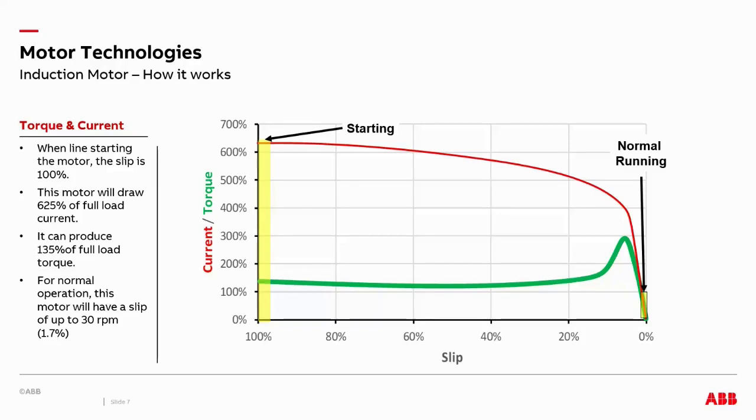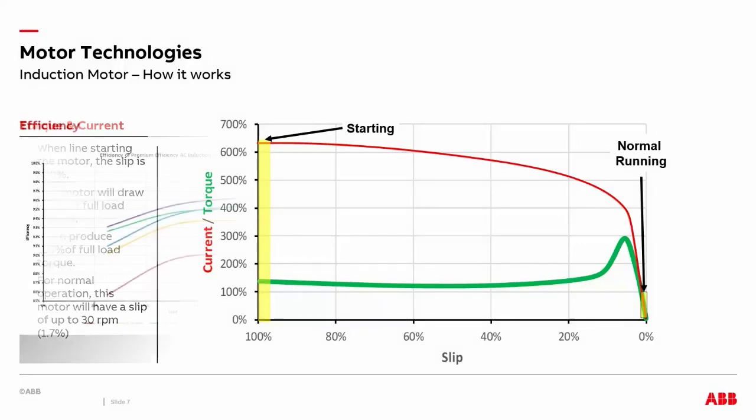So we reduce mechanical stress. The power factor on a drive improves it on your system utility. Usually the power factor on an induction motor is a little less than if you would put it on a drive. And most importantly, energy savings. By operating the load at the required flow, this eliminates any need for mechanical means of flow regulation.